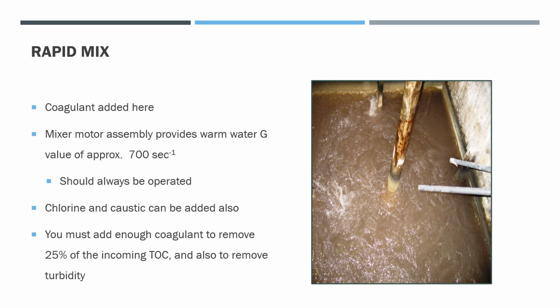Remember, operators here have to add enough coagulant to remove 25% of the incoming TOC, and of course also to remove turbidity. And unlike most Lake Erie water treatment plants, more coagulant is needed to take out TOC than is needed to take out turbidity.